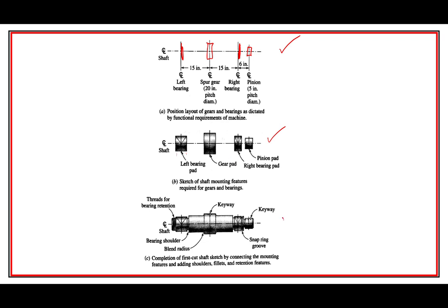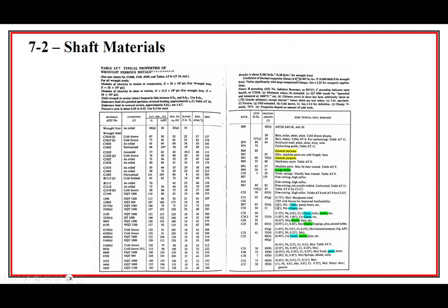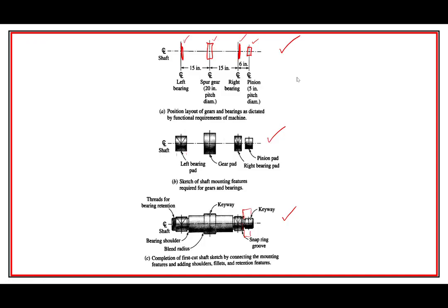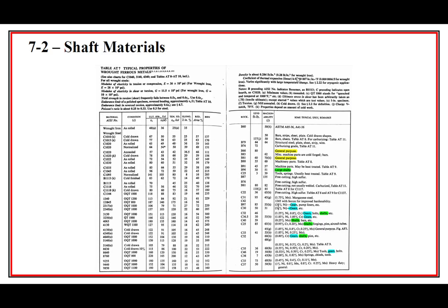And then we have to design the shaft, and we like to have locations where it has a step here to make sure that when installed, these gears and bearings are exactly where we want them to be lengthwise, axially. So there was some discussion in the layout. Shaft materials. This can be quite complex.